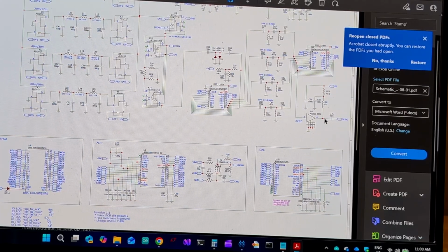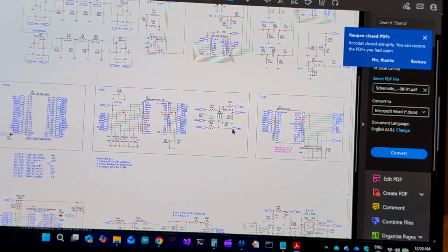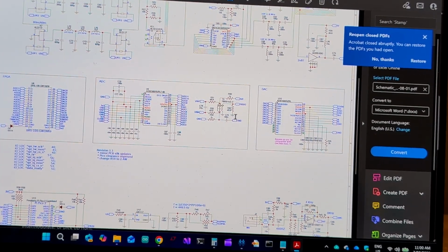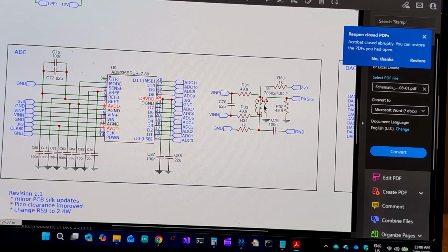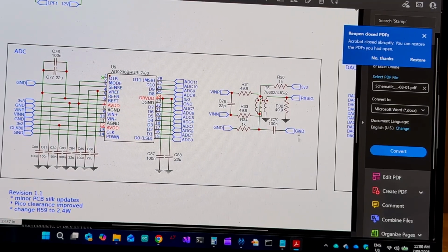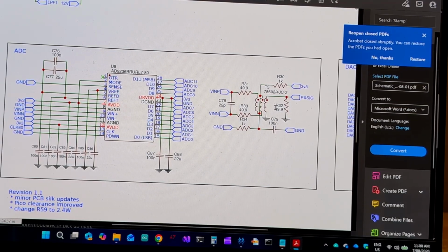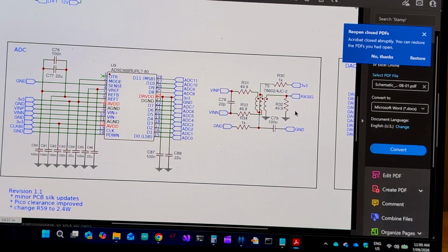The output from the MMIC goes to a single-ended to differential transformer here. It's a trifilar transformer. So what we get here is, because this is trifilar, you get basically 6 dB of free gain. Now, why do we have this 50 ohm resistor here? Well, the 50 ohm resistor provides the correct load to the MMIC and therefore to the filters.